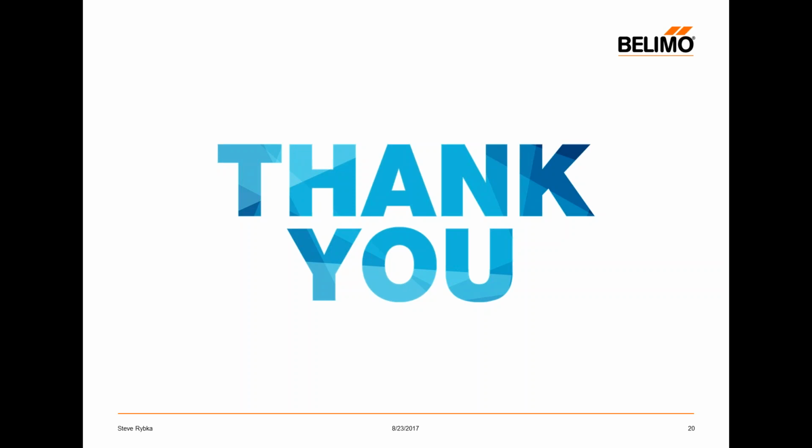Does the Belimo energy valve go away from using CV sizing? Is it more based on GPM? It's totally based on GPM.